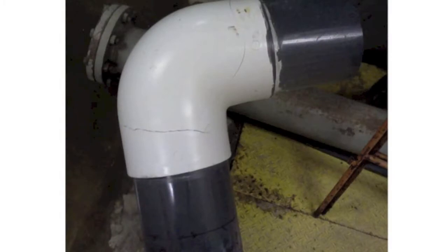Now let's talk about the effects and mitigation. The water hammer effect is similar in both residential and commercial applications. In residential applications, you'll mostly just hear a thud if the valve is shut off too quickly. If the water hammer effect is strong enough, the pipes can actually be blown apart. An example of this took place right here at the Fluid Dynamics Laboratory. While the pump was running, the valve was quickly shut and resulted in a glued-on elbow joint being blown off the pipe. The water hammer effect is also present in more extreme situations. For example, watch what happens when a storm drainage system experiences the water hammer effect.